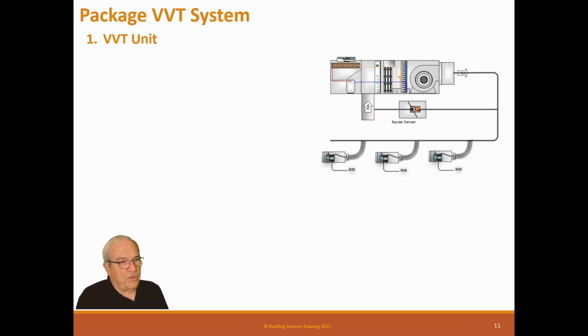And if you have a return damper in there, a return grill, it'll dump that cold air supply duct right down on the floor because it wants to go down, right? So the cold air will hug the bottom of the ceiling, and it will drop right out of those ceiling grills. So eventually we got the idea to put this hard duct up, and that actually worked. When they were just open, it didn't work at all.